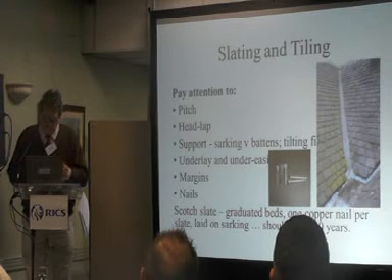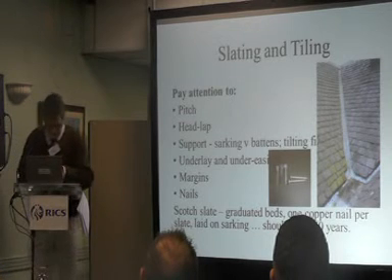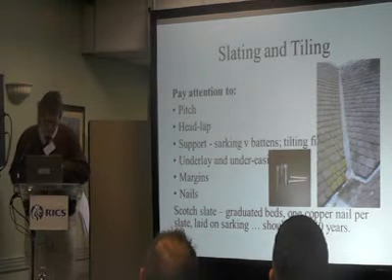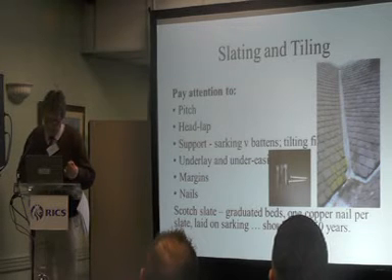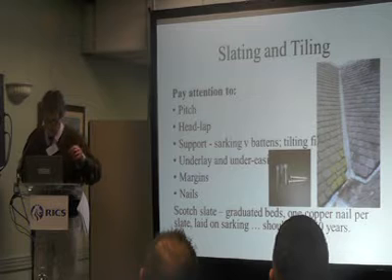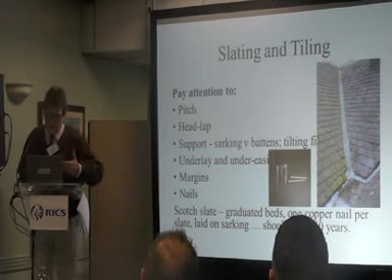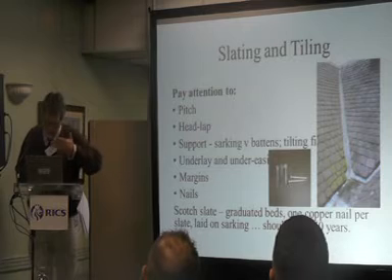Underlay and under eaves, I don't know what's happened to the size of my text here. It's slipped, I think, since I wrote it, but there we are. Even though you're going to puncture this membrane with every nail that holds on every slate, it's actually still worth having. It does stop a bit of the draft, it does stop some of the moisture and push it down the roof.